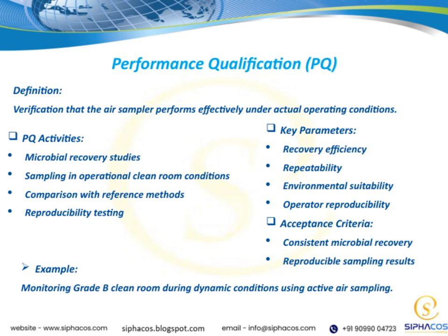Now, let's consider the PQ activities. These include microbial recovery studies, where we test how effectively microbes are recovered during sampling. We also perform sampling in real operational clean room conditions to see how the method performs in the actual environment. Comparing our results with reference methods helps us validate the accuracy of our approach. Reproducibility testing ensures that the method yields similar results across different tests and operators.